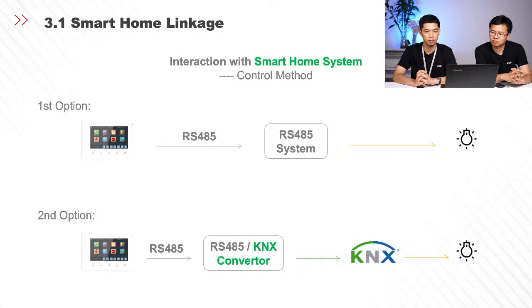with our KNX system. So in this case, the monitor still sends the RS485 signal, but then we will use an RS485 to KNX converter to convert the telegram into the KNX part, and then move to the KNX device, and eventually to control the light bulb. So it means that we should configure the ETS software for the smart home, and then integrate the smart home features through this converter. Yes, of course, because it actually combines 2 parts, both the KNX part and also the RS485 integration.